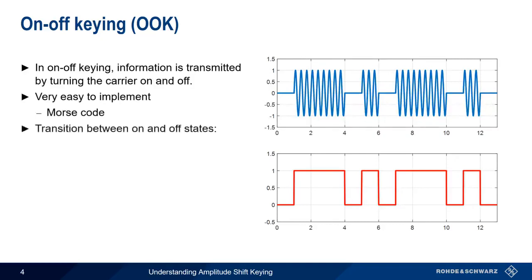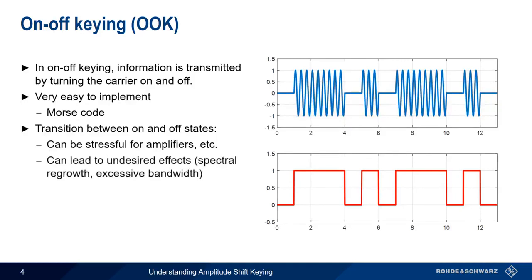However, this transition between off and on states also has some potential disadvantages. It's more stressful for amplifiers and some other types of RF components, and the rapid rise and fall times can create undesired effects, such as spectral regrowth.